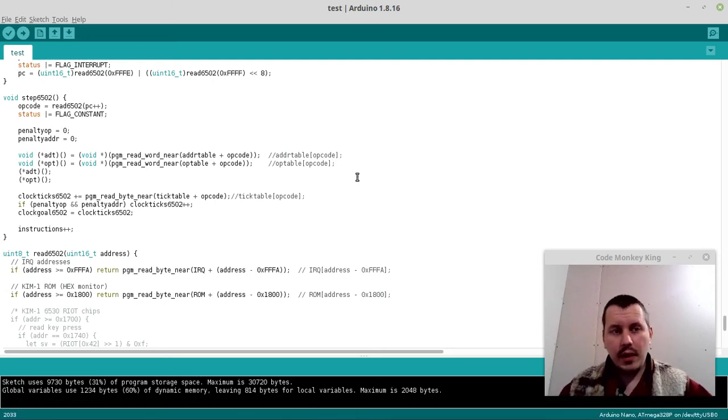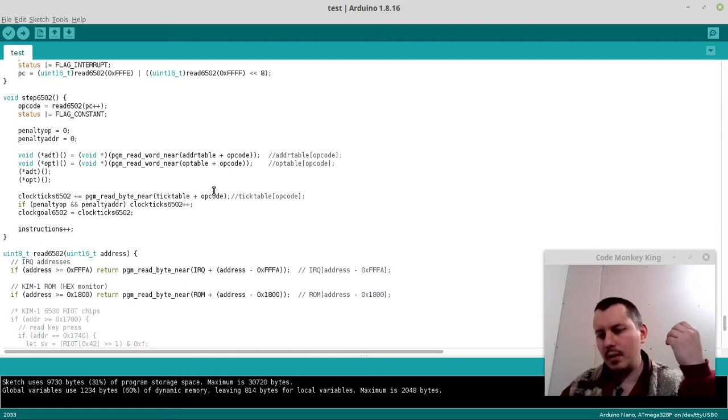KIM here. So I've connected the KIM-1 ROM to my 6502 CPU emulator, written by Mike Chambers, that I've adapted to run on Arduino. The ROM is also going into PROGMEM, obviously, because otherwise it not only wastes the entire RAM, but it doesn't even fit into RAM, because there's only 1K of RAM for Nano and Uno Arduinos. It's 8K for the Mega that I'm going to be using later on, but again, I'm just debugging on the Nano because I want to make sure it runs on the minimalist setup, and then obviously the extensions are possible.